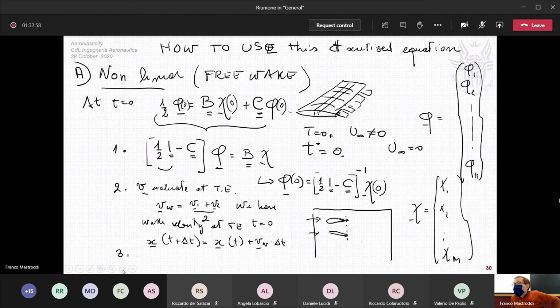Why can you do that? Because you know that, put a condition, there is a continuity of phi upper and down position, and this difference of velocity potential can be convected in the wake regularly without any trailing edge sink effect or source effect. You can smoothly convect this continuity in the wake, and so you can locate this delta phi in the first row of wake panel you are generating.